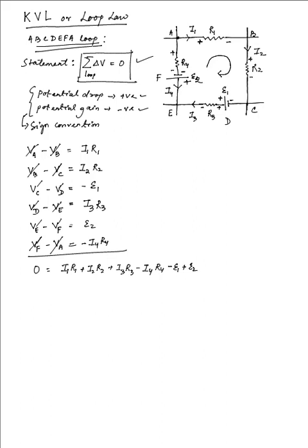But because there's a zero on the other side, we can just interchange those signs, but we are not concerned about each and every sign over here. We just take the EMFs onto the other side, E1 minus E2, and we keep the product of the resistance and the currents on the right hand side, I1 R1 plus I2 R2 plus I3 R3 minus I4 R4 remains as such.